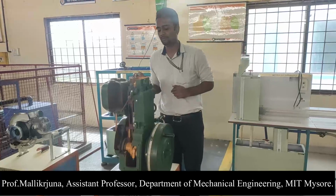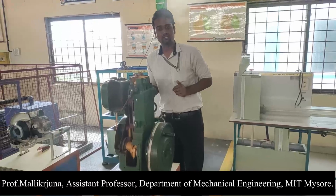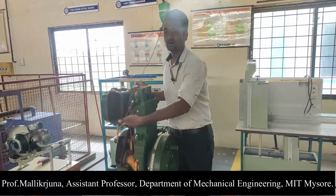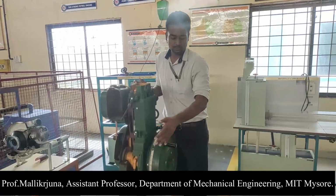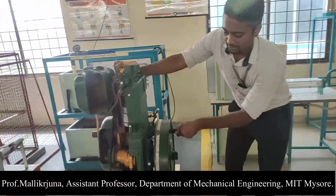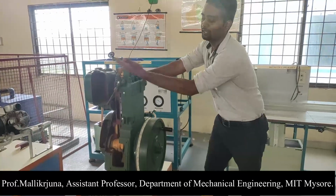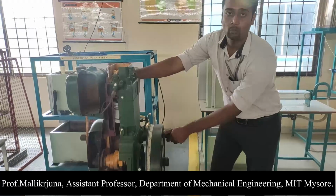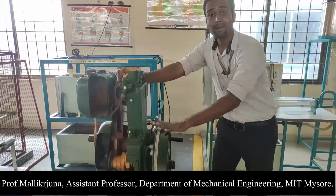If we want to conduct the experiment, we need to be very careful. So let us start the experiment from the first stroke, which is nothing but the suction stroke itself. I need to adjust the flywheel in such a way that for the suction stroke, the piston will be at TDC. Let us adjust the flywheel. This flywheel needs to be given the motion from this side, in clockwise direction. If I look from the engine side, it is an anti-clockwise direction. If I look from this side, I have to give a motion in a clockwise direction so that I can perform the various operations manually.